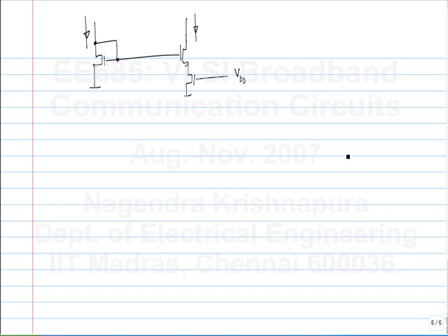How do we make them equal? So you can put the same switch here and connect it to VDD. Okay. And this can go between VDD and ground. So when it's connected to VDD, the two sides are similar, so you get accurate current mirroring. Okay. So is this better than switching at the drain or worse? Better. Why?